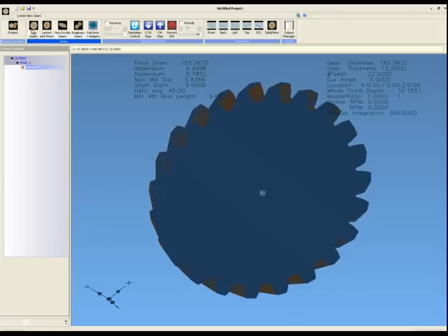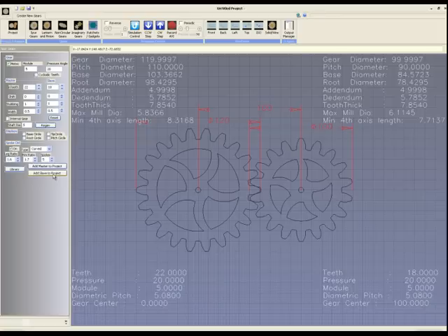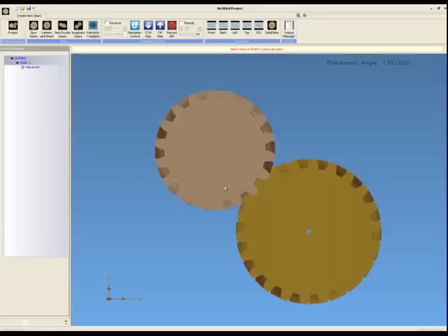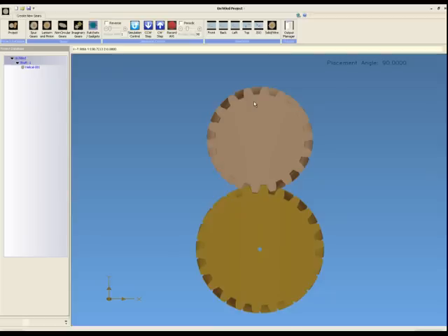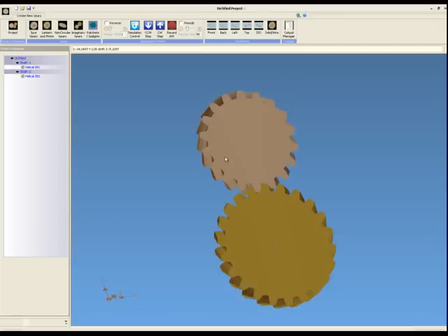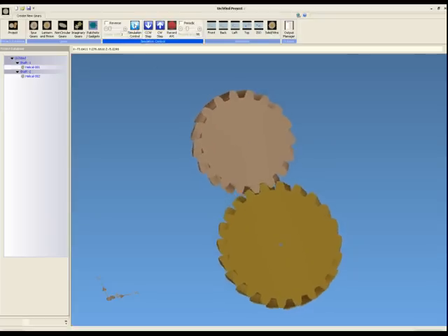Now let's go back to the Spur screen and create another helical. I'm going to say add slave, although with helicals I could just as easily say add master. Helicals don't care what a master or slave, they're not matched that way. So let's select helical, and let's select another 45-degree helical, and I'm going to select left-handed. If two helicals are meshed, one right-handed and one left-handed, they will sit on an axial plane. So we'll roll this helical around and stick it on, and by clicking we'll set its location, and you can see now I have two gears on the same axial plane. They mesh well, and they will run together when simulated.